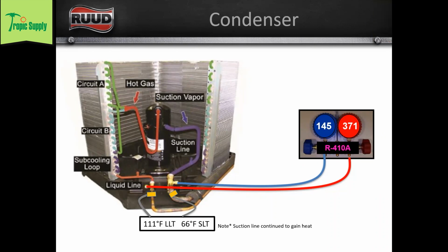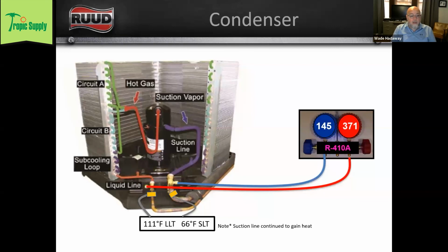And one other question, sorry. So these are all on split systems. What would change if it was a package unit? Same thing. You're going to consider everything the same way. You're going to measure everything, a little differently in different locations, just because of the differences between a split and a package unit. But you're still going to check your suction line temp when you're reading superheat coming out of that evaporator, coming out of that indoor coil.